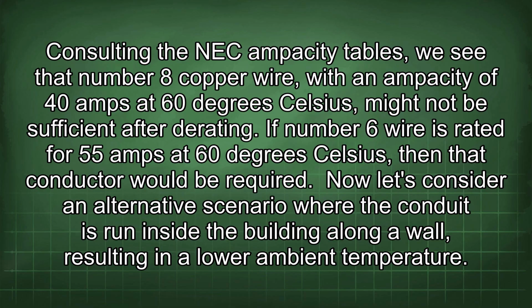Consulting the NEC ampacity tables, we see that number 8 copper wire, with an ampacity of 40 amps at 60 degrees Celsius, might not be sufficient after derating. If number 6 wire is rated for 55 amps at 60 degrees Celsius, then that conductor would be required.